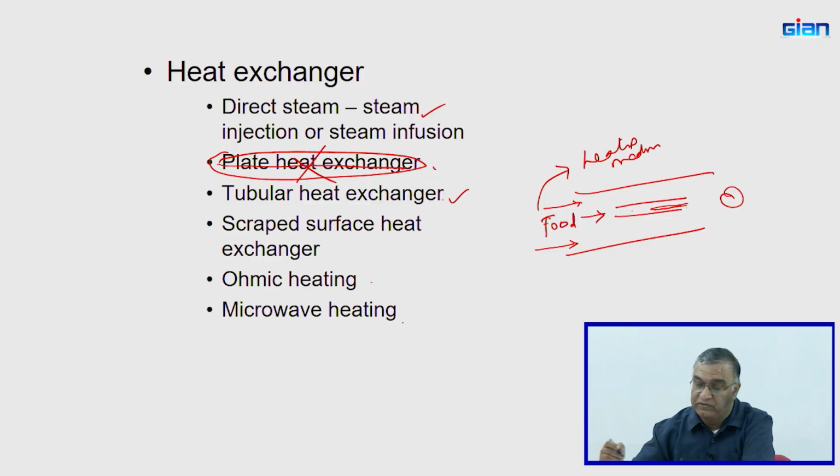Why are we doing that? For example, when you process protein products, maybe starches and so on, when you are heating them, the material can deposit and form what they call biofilm or something along those lines, and they can reduce the heat transfer efficiency. To facilitate removing some of those deposits and also to facilitate mixing, you normally use this rotating mechanism.